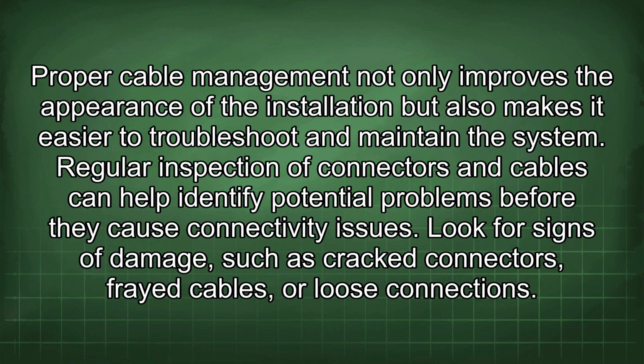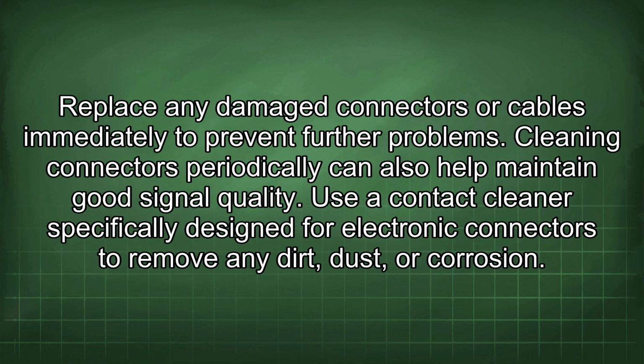Look for signs of damage, such as cracked connectors, frayed cables, or loose connections. Replace any damaged connectors or cables immediately to prevent further problems. Cleaning connectors periodically can also help maintain good signal quality. Use a contact cleaner specifically designed for electronic connectors to remove any dirt, dust, or corrosion.